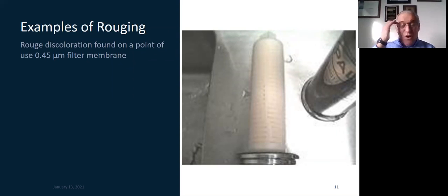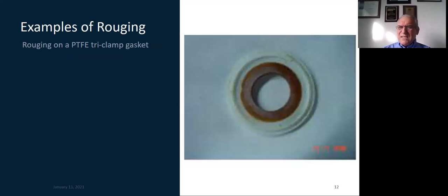Deposition means that all different pieces of plastic and non-metallics in water systems, including gaskets like ETFE, PTFE, etc., have a slight negative charge. And that slight negative charge will adhere and attract positively charged particulates, in this case iron oxides and ferric oxides. What most people don't know is that these non-metallic gaskets and materials can attract rouge, which is a good thing because you're stopping the rouge particulates from cascading down into the water system, down to the points of use.